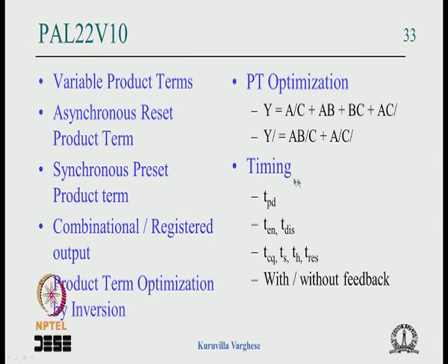And there is timing; maybe we will talk about this timing in the next lecture. So you have propagation delay, you have output enable and disable timing, and the flip flop delays like TCQ, setup and hold time, and the reset delay and all that. These are the timing parameters. In the case of 16L8 it's just a 1 section delay, there is nothing more to it.